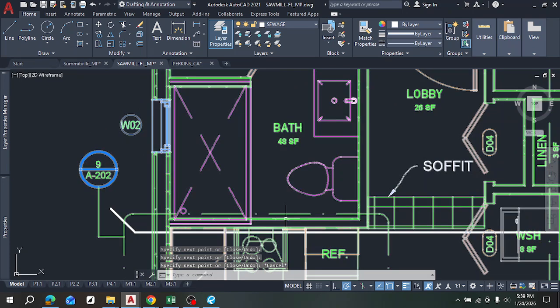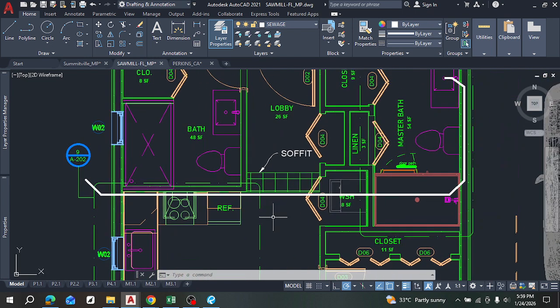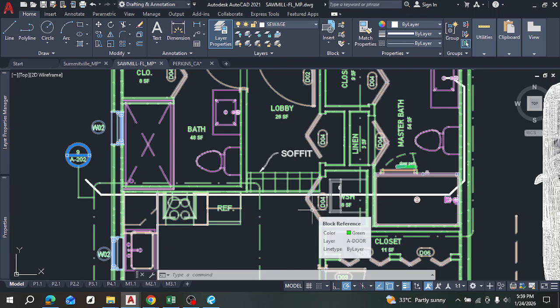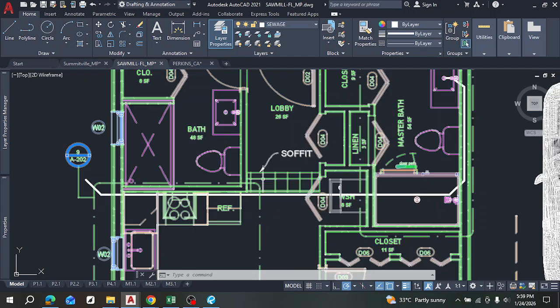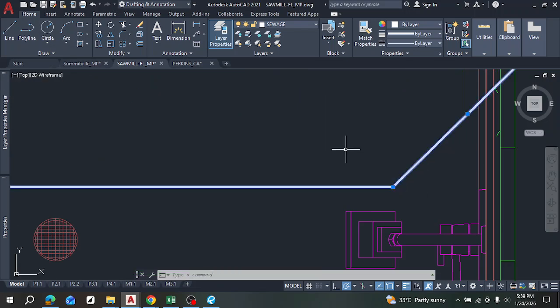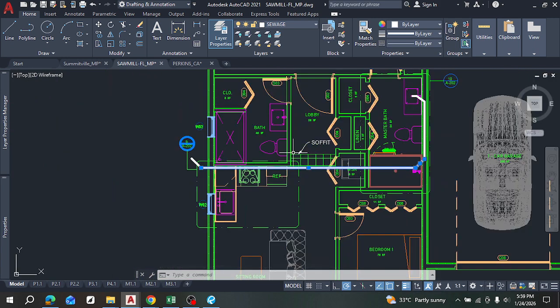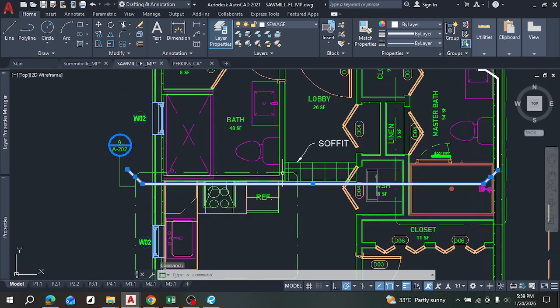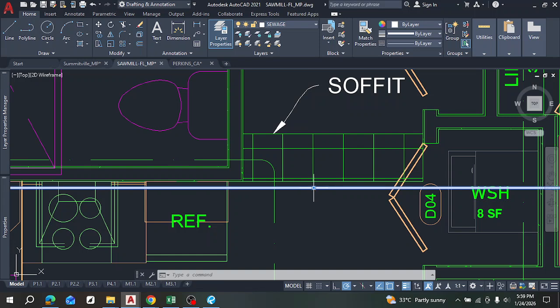I would like this to pass within this wall, right? Because this is the kitchen space, and like I think I mentioned very early in this course, routing drainage lines, you have to be careful, or you have to be specific about not passing through eating or living areas. Avoid them as much as you can, right? I mean, odds of leakage is very low, but if it should happen, let it happen in spaces where, if the owner of the house or the building is there, it's not going to inconvenience them too much. So I want to move this up, that is out of that kitchen space.